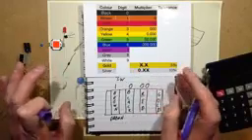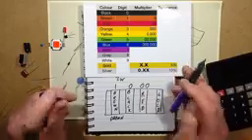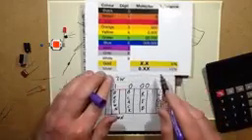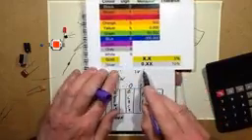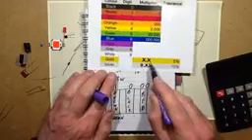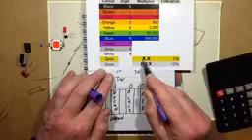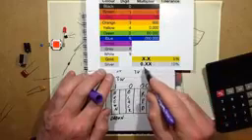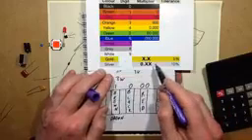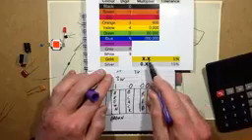If it's going to be a much lower value, like 4.7 ohms, you'll get basically a divider, either gold or silver. If the first two digits are followed by a gold band, it will be first digit, point, second digit. So for instance, 4.7 would be yellow, violet, gold.